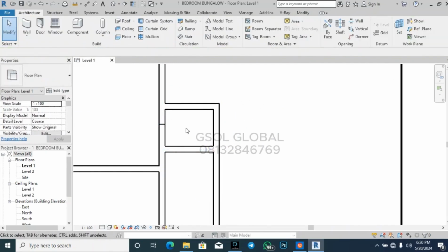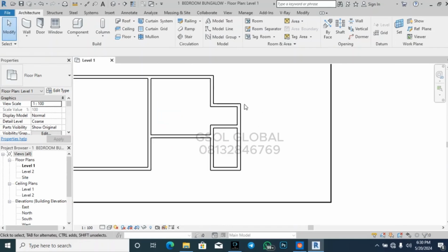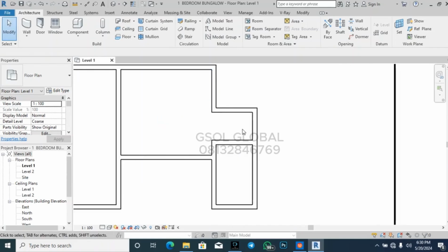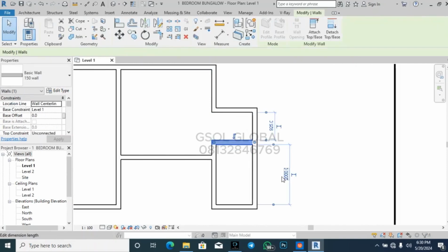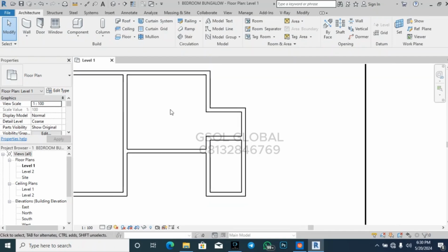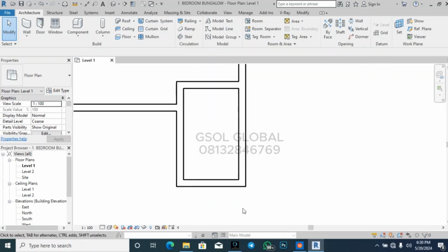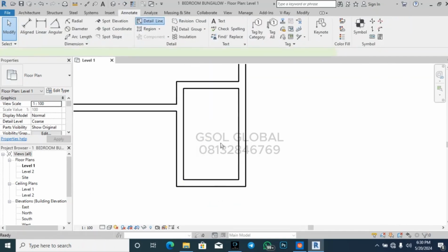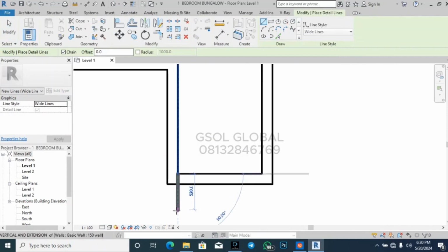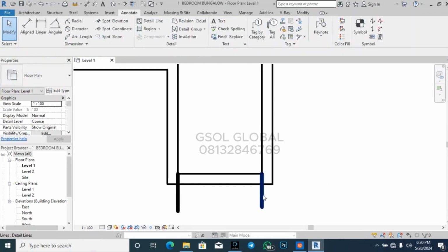All right, so we are entering into the main deal now. Let's take note. So we have to create an access in this place. So now I'm having 2 meters, right? I'm having 1.2 meters, right? Your 1.2 meters is in to in. That's what we call in to in. What I mean by in to in is from this point to this point, not from outside to outside.